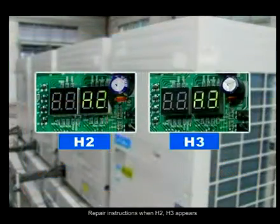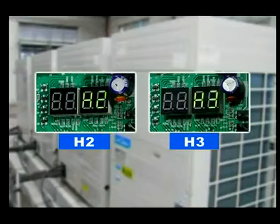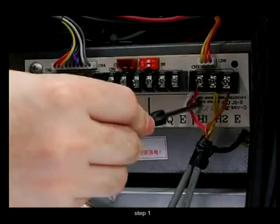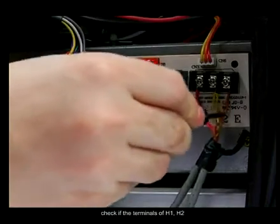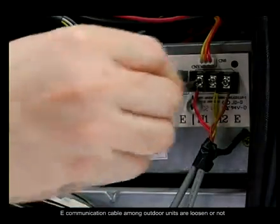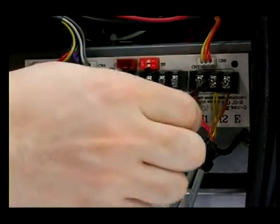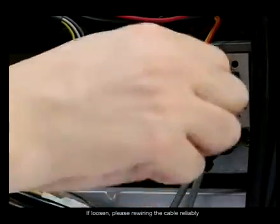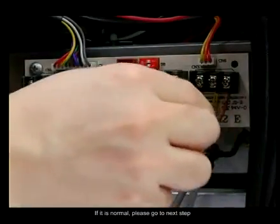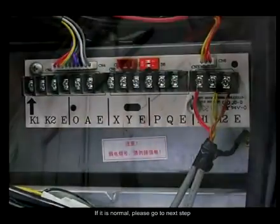Repair instructions when H2, H3 appears. Step 1. Check if the terminals of H1, H2, E communication cable among outdoor units are loosened or not. If loosened, please rewire the cable reliably. If it is normal, please go to the next step.